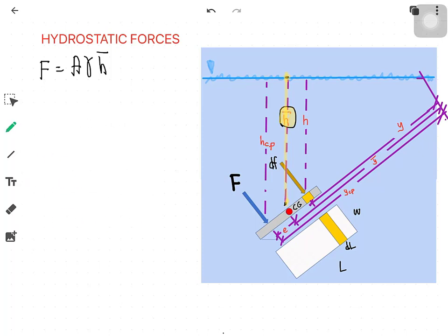So let us recall from Pascal's law that at any point in a fluid at rest, the pressure is the same in all directions. From that statement, we may say that the pressure distribution in this gate in our example, submerged in water, is the same in all directions. So from the previous formula, the pressure P is equal to the force applied over the cross-sectional area of your object. If we cross-multiply this equation, we get that the force is equal to the pressure times the cross-sectional area.